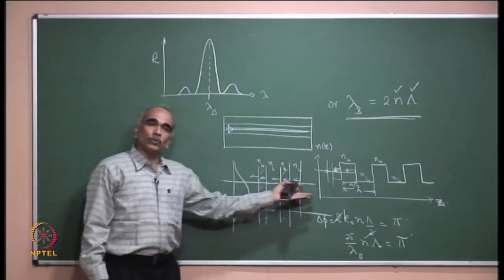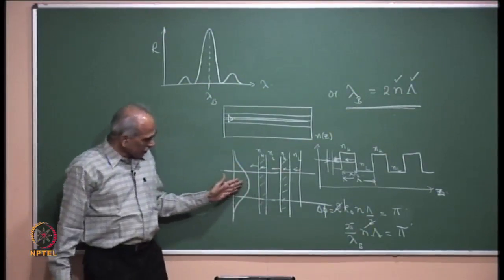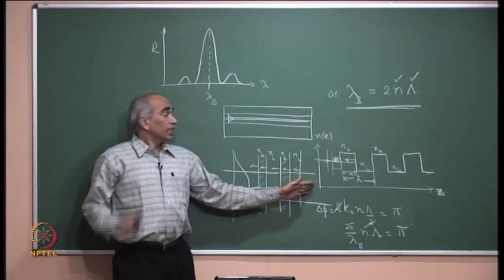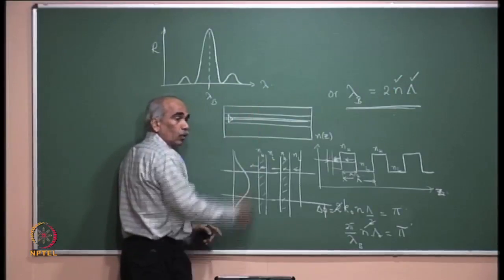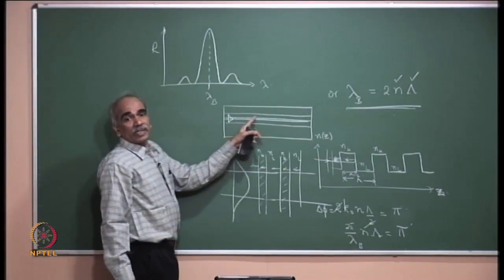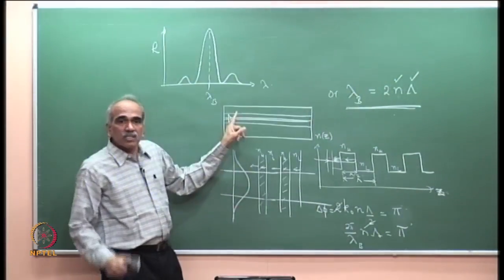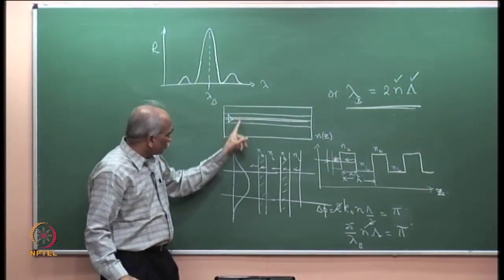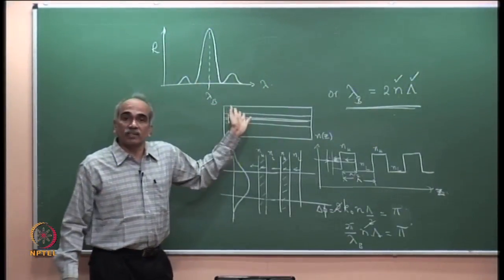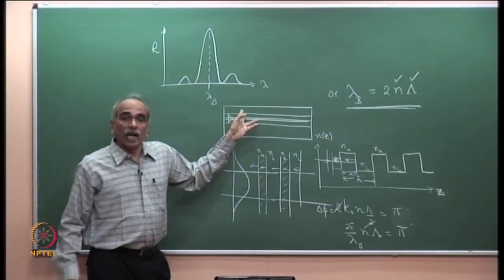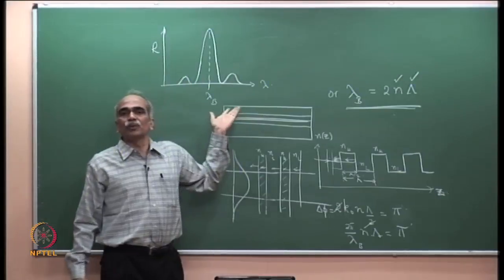It is the same which you see in fiber Bragg gratings also, where the grating is written right into the core. In the case of semiconductor lasers, you could have written grating in the core, but you do not try to write a grating in the core, because any fabrication step which introduces some variation here will also introduce defects in the active region, and the active region or generation of light is highly sensitive to defects.